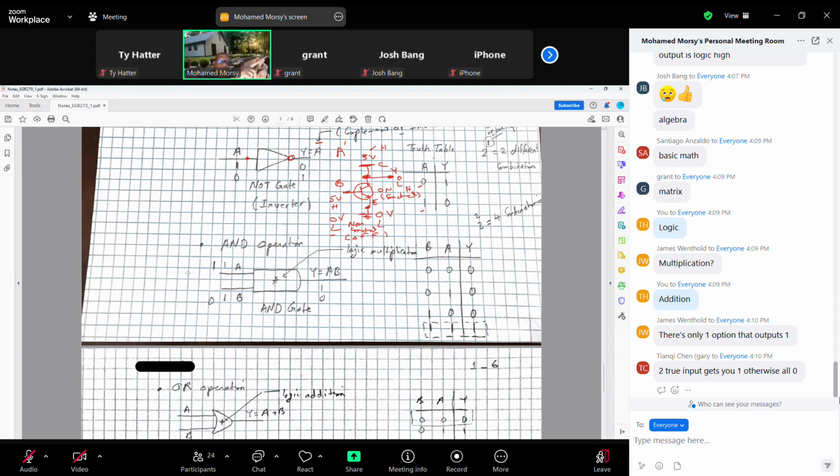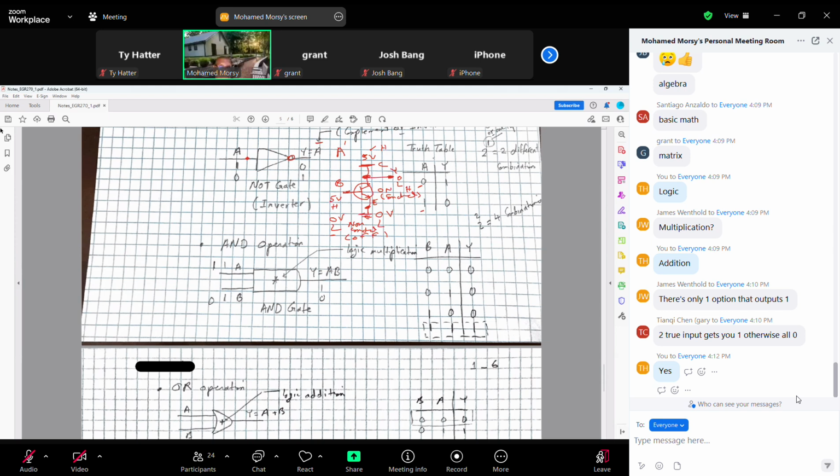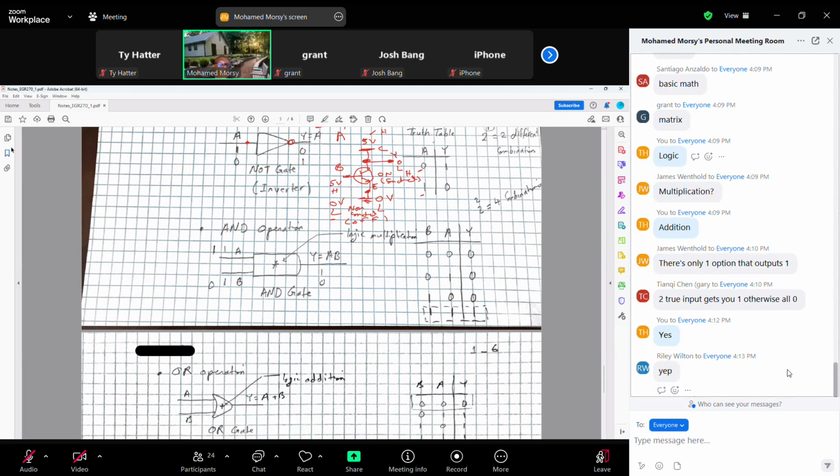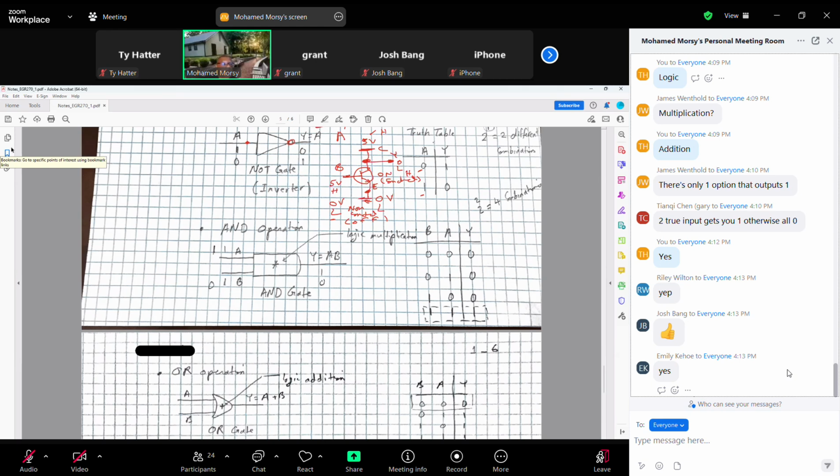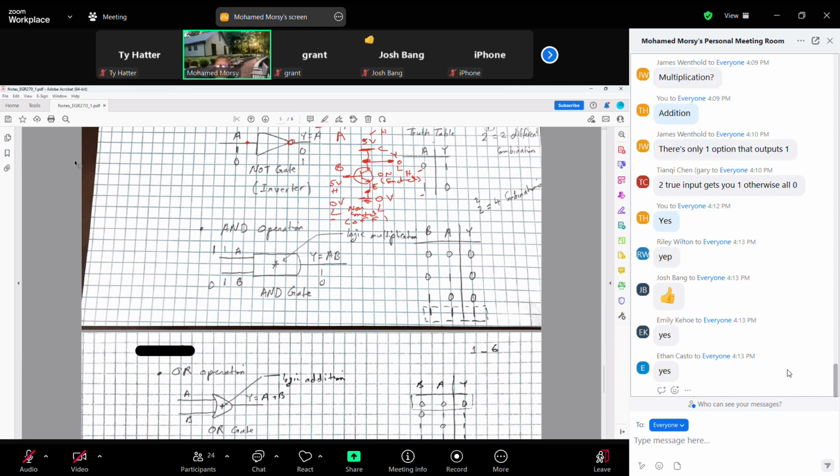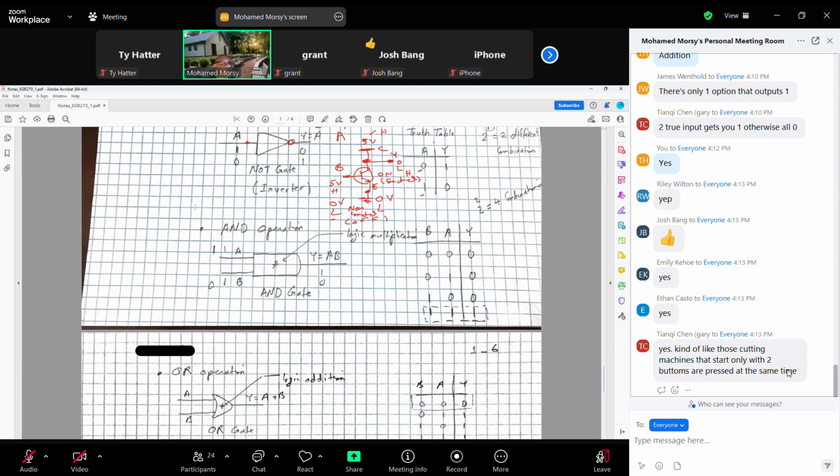So we look at input A and input B, and we draw the transitions for the bits. When both A and B are ones, the output will be 1 for that time duration, and then 0 until we see both inputs are ones again. Okay? Does everyone see what I'm saying? Please say yes, or if you have any question, ask me, please. Okay, good. If you don't have questions, this means it is okay. That's what I understand. Please tell me if you have any question.